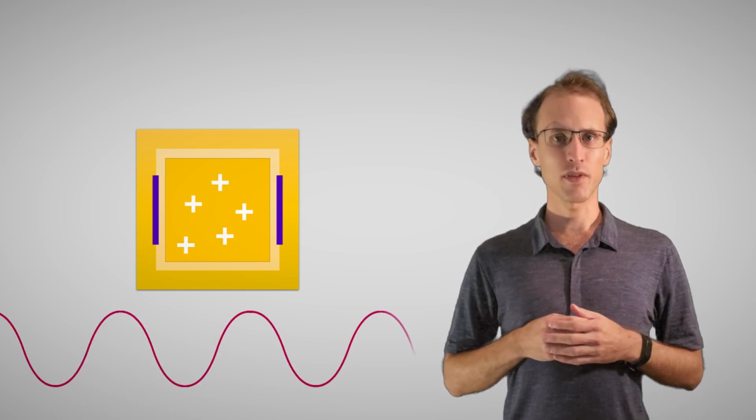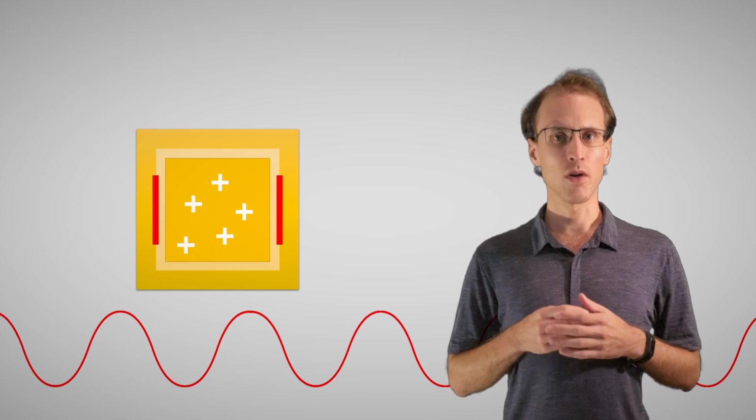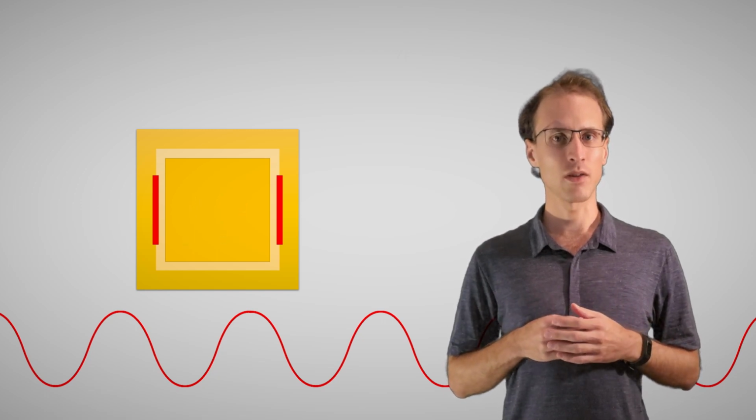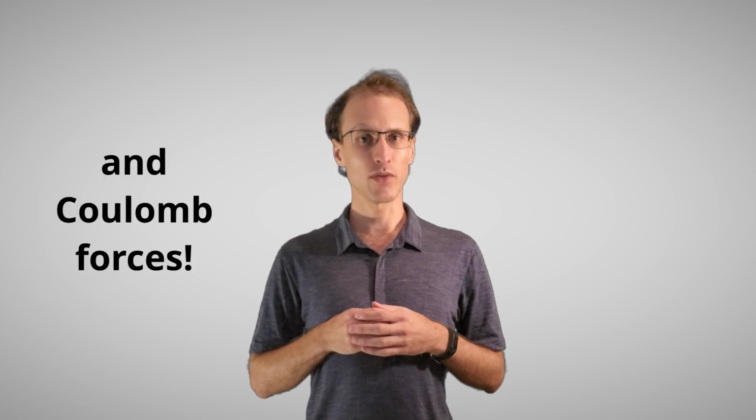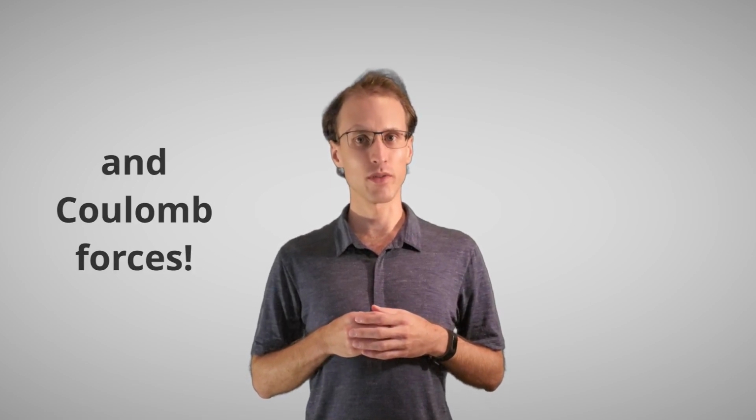Unfortunately, the test mass capacitive control and sensing system only works if the test mass is at or very close to the spacecraft ground. Not only is this a catastrophic controls issue if left unchecked, charges on the test mass can interact with stray electric fields of other componentry in the spacecraft via Lorentz force coupling. It is this noise source that we call charge-induced force noise.